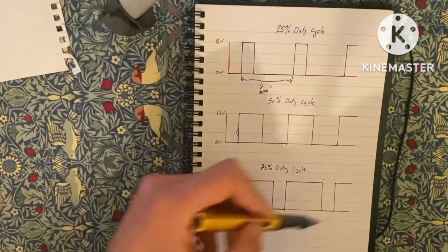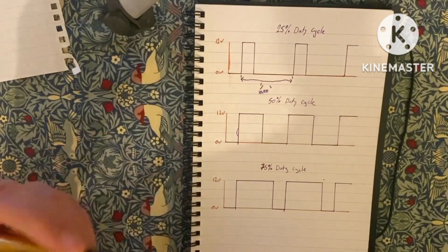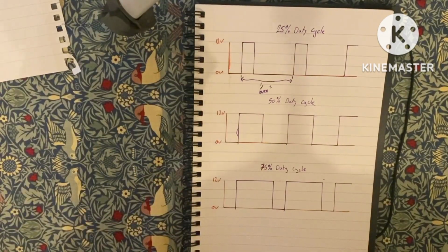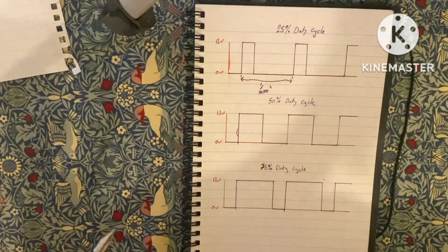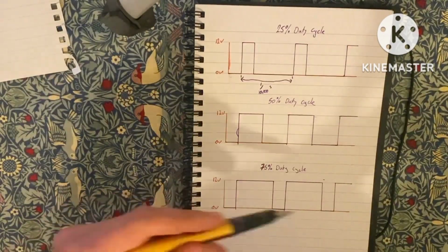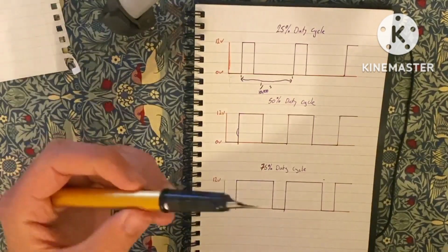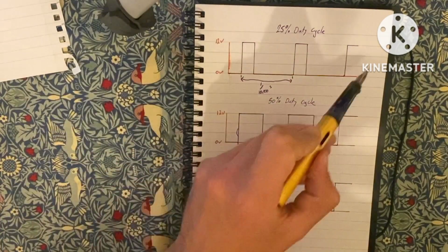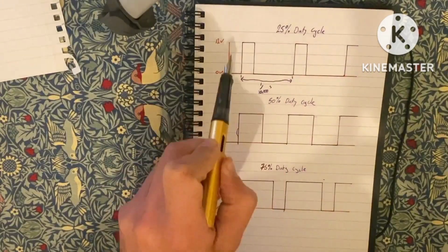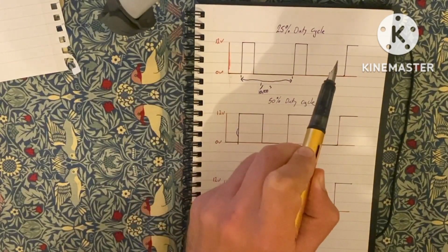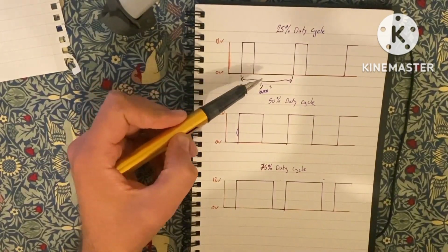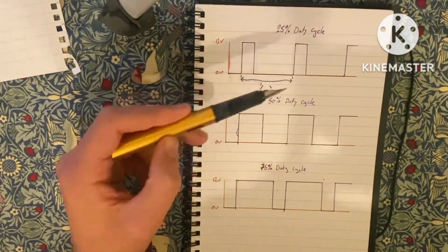Now, because this is operating at 10,000 hertz, it's far too fast for the human eye to actually see this light turning on and off, on and off, on and off. So what our brain does is it stitches all these fragments of images together. And what it results in is, in this example, our eyes would see the bulbs looking relatively dim because they're only on for 25% of the time that our eyes are actually seeing them.